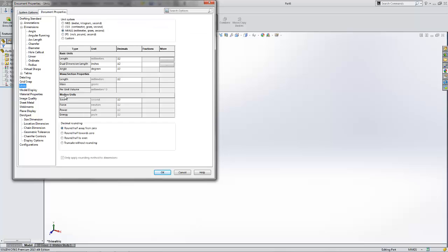Another thing I might want to change for a template are going to be units. Again, maybe millimeters aren't what I constantly work in. I could potentially be working in angstroms. And I want to show a dual dimensional length of inches, so I still have an idea of what I'm doing, because I'm never modeling angstroms. And I'll go ahead and keep my angle at degrees. These things will get saved in this template, so I could very easily create a new angstroms template from this particular interface.